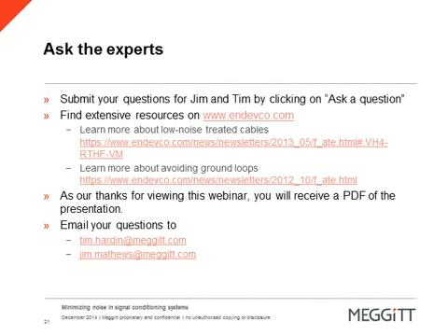Excellent point, Jim. Another question. We typically use a case-isolated IEPE accelerometer, but we do not have very good history with the isolation quality and have to add a very thin isolation between the accelerometer and the UUT. Is this a common issue?